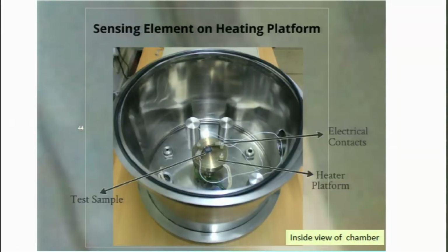Now, we want to test these small platforms which we have developed, these small films, for their sensitivities related to the presence of hydrogen. Hydrogen is otherwise a reducing gas, so it will enable some hydride states and try to change the resistance of the material, and we can see what the difference is between a continuous material and the porous material that we have developed. So, for that we have a